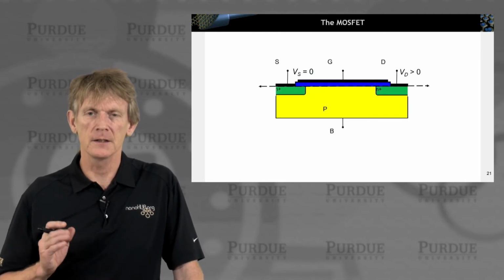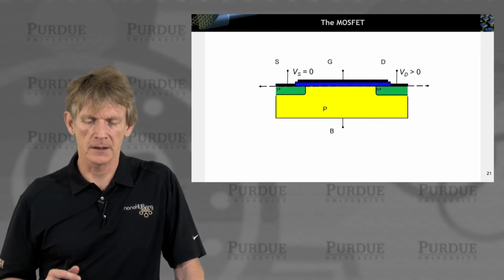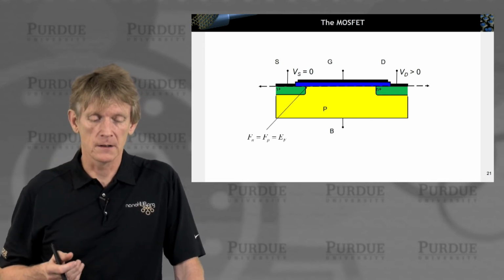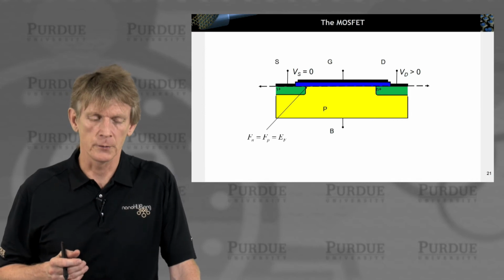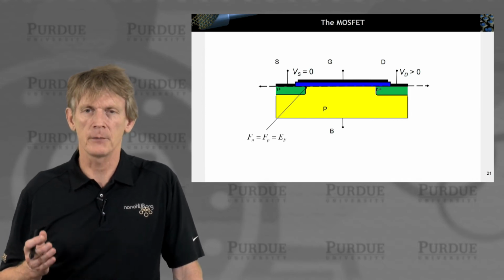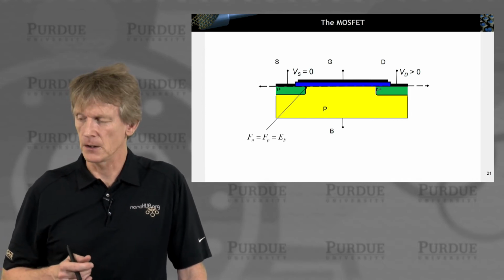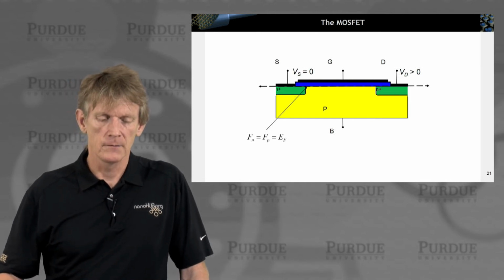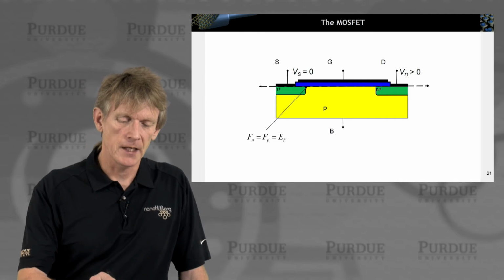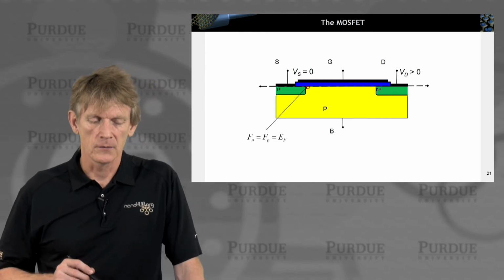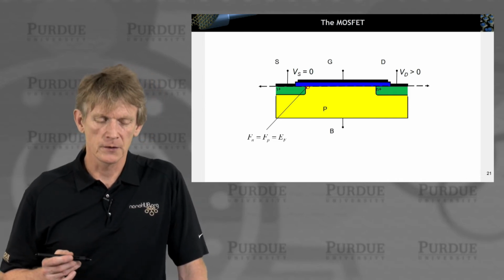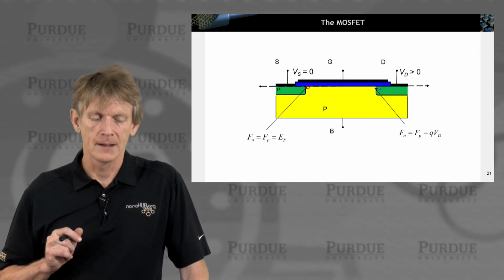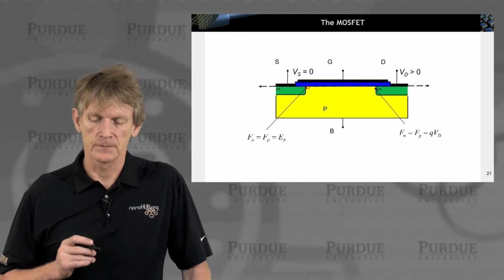All right, so here is the sketch of the MOSFET again. And we now are dealing with different Fermi levels and quasi-Fermi levels in the structure. And we'll take a couple of different slices throughout the device. All right, so here at the source gate entry, we have the 2 different quasi-Fermi levels to be the Fermi level of the source.